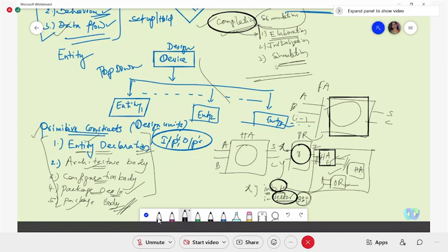So in your simulation segment, the elaboration, the initialization, and simulation will be done. It's not just simple simulation and compilation. The compilation is checking of the syntax and generating the netlist. Simulation is elaboration of the netlist and initializing the values, and then simulating, which generates the waveform analysis window. Okay, these are the stages what you have.